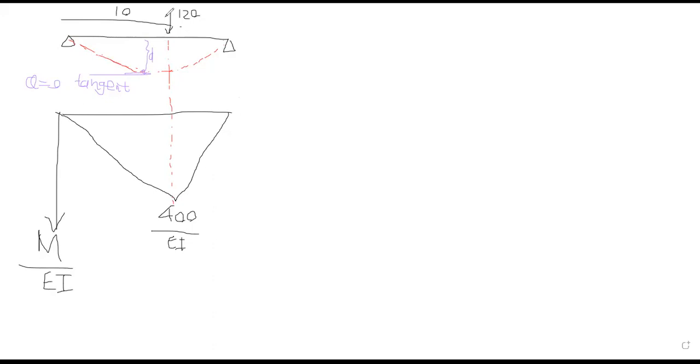If you just take a flexible ruler and apply some load like this, you will see the maximum deflection would be somewhere around here. But if you draw the bending moment diagram, the maximum bending moment is just underneath that, right? So the maximum deflection is somewhere here. So I will consider that as xm. Okay. So for that, I will take, this is the bending moment, right? So this is xm.